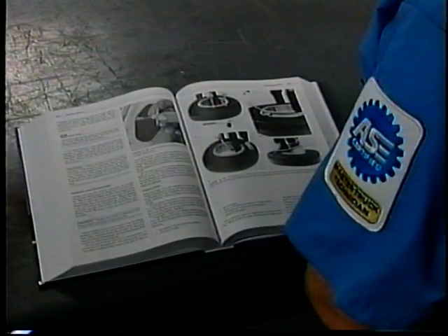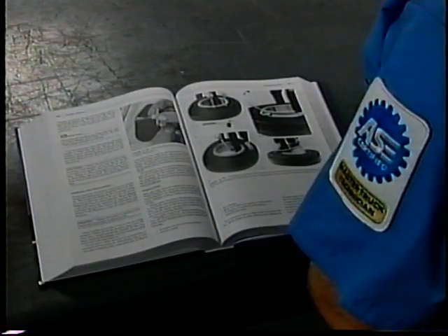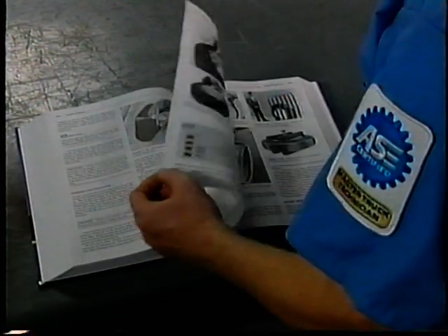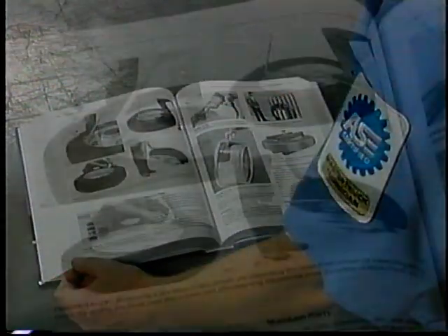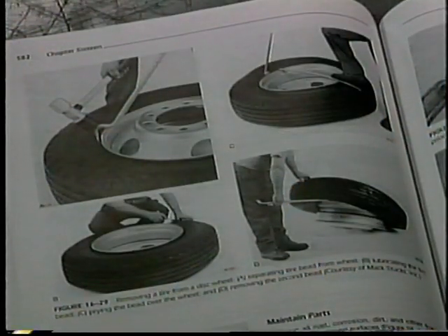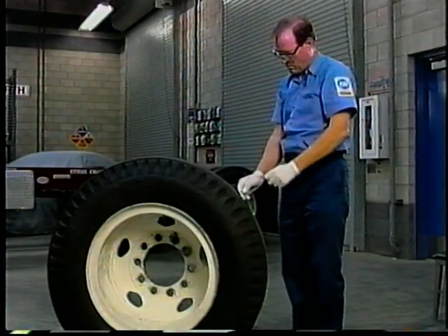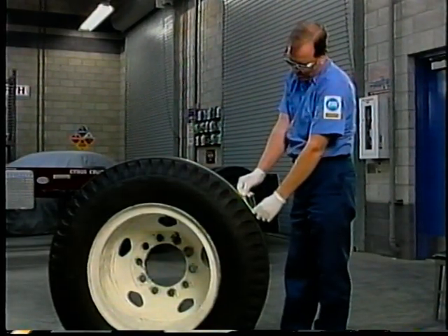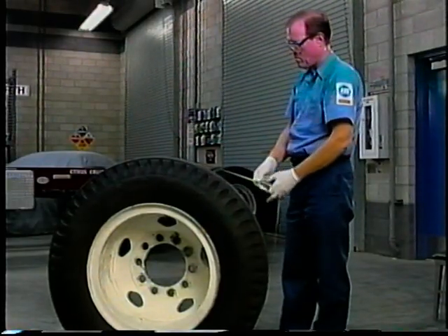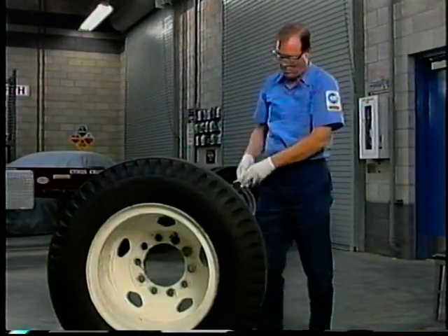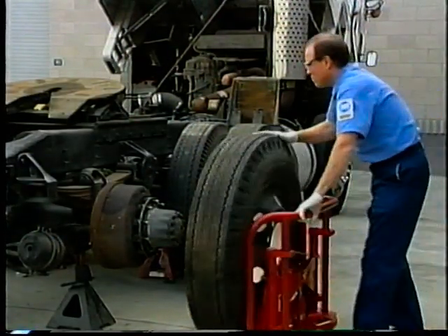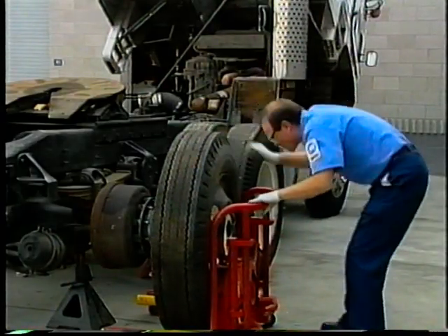Always follow the procedures to dismount tires step by step. Always use a tire cage to dismount tires. Regardless of how well you think you know the proper dismount sequence, always refer to the procedure before attempting to dismount a tire. When replacing tires, never mix radial and bias ply tires on the same axle. Mismatched tire sizes will lead to excessive tire wear. Measure the tire sizes with a tape measure or caliper before installing. When installing dual wheel assemblies on the drive axle, lightly lubricate the spindles and use a thread protector.